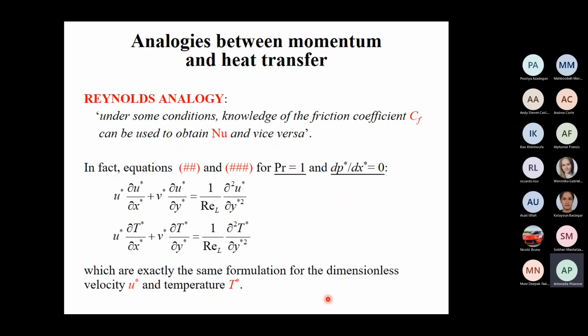A brief comment on Prandtl number equal to 1. If you remember, I said to you that a lot of engineering fluids, so fluids that are used by engineers, that means in our plants typically water, air, and refrigerants, can all be considered with Prandtl number on the order of 1, not exactly 1, but if I have Prandtl equal to 3, it's the same as for 1. So the behavior can be approximated as for a fluid with Prandtl equal to 1. It's different for the case of oils or liquid metals, for which the Prandtl number is really different from 1. For engineering fluids, the Prandtl number frequently can be considered as 1, and so I can use this approximation. I can neglect the Prandtl number and I can use the Reynolds analogy.